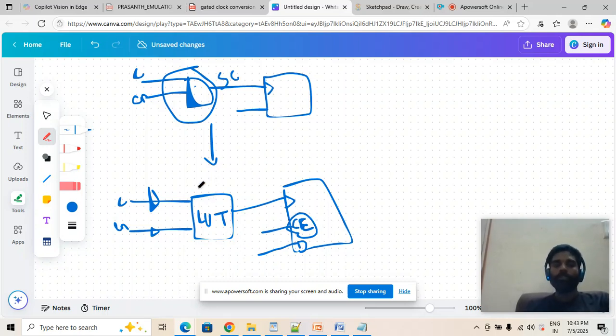So now how do we convert? We don't want this LUT to be inferred and then go to the clock, right? So what's the problem? When we do timing analysis, it may create some skew, like in the combinational path, right? In the clock path, we have some combinational path also here, right? Because the clock is coming, and if this is the data path, this is the clock path. We're just mixing these paths, and this will create some combinational delay, and at the same time some skew and all. So during timing analysis, it's going to be a very big headache for us.